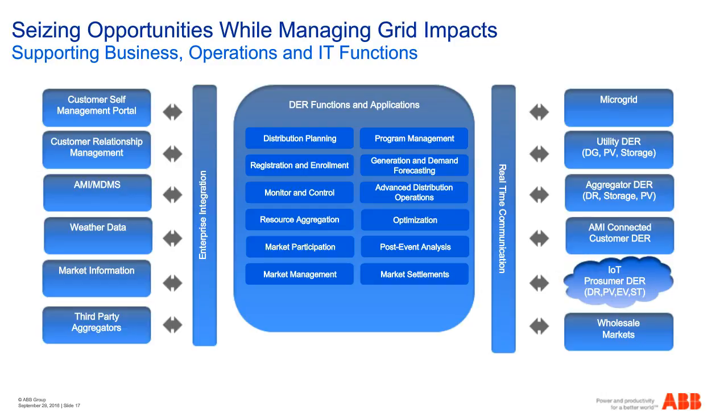The DERMS should be integrated into your advanced distribution management system. And in fact, a lot of ADMS vendors are viewing DERMS as a natural integrated extension of their ADMS. This provides fine-grained forecasts for DER generation and demand, and provides important input to the ADMS applications such as state estimation, FLISR, and VVO, VVC.